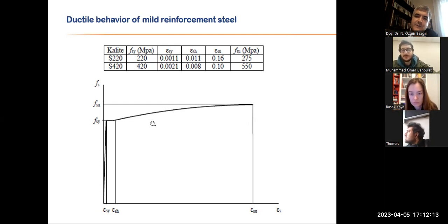When we take our seismic forces and divide them by 8, for example, our R value, and design for 1/8 of the value, if the earthquake hits, it is going to force the structure all the way into this region, right? Yes. This is a part of our ductility. That could be a part of the question. And of course, the R value is not a sole quality of just the reinforcement, but of how the structure is composed. That's also related. And when you are now in this region, your structure is not as before. It has deflected tremendously, right?